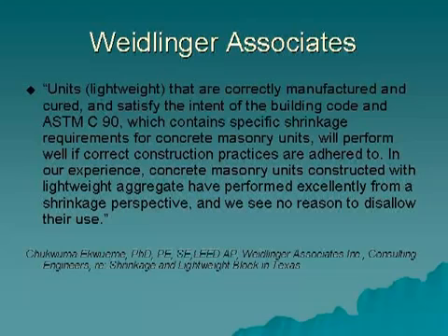Quote, "Units, lightweight, that are correctly manufactured and cured and satisfy the intent of the building code in ASTM C 90, which contains specific shrinkage requirements for concrete masonry units, will perform well if correct construction practices are adhered to. In our experience, concrete masonry units constructed with lightweight aggregate have performed excellently from a shrinkage perspective, and we see no reason to disallow their use."